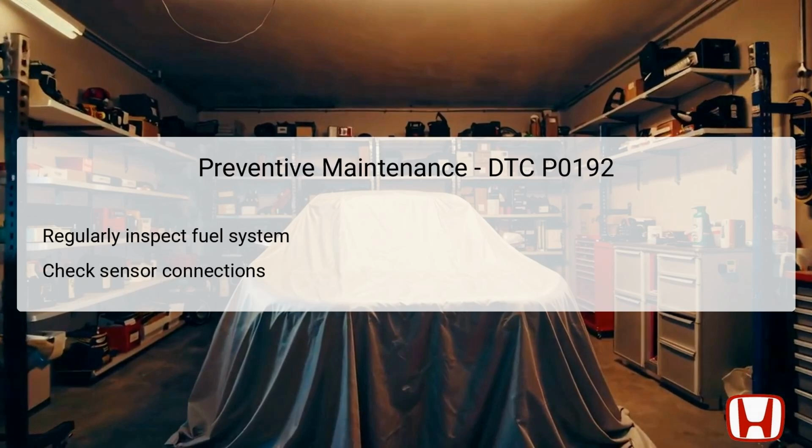Ensuring voltage supply lines and ground connections are secure promotes the reliability of the sensor. Additionally, performing regular maintenance on the PCM software can enhance vehicle performance and prevent misreadings or confusion triggered by outdated programming. By implementing these preventative measures, vehicle owners can prolong the life of their fuel system components and maintain optimal engine performance.